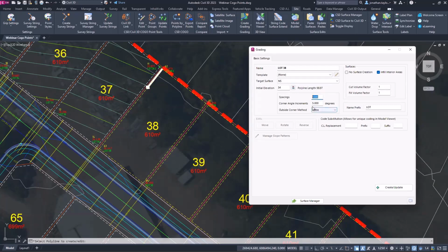When you have a spacing of 1,000, all that means is that it's only going to show you in the cross section, in the long section very shortly, the sample positions at the horizontal geometry points only, which, to be fair, are the only points I want to edit anyway, okay? So having a big spacing value on these initially can be helpful, but you can try it yourself. You can put smaller spacings, and then as the job grows, maybe look to increase them.